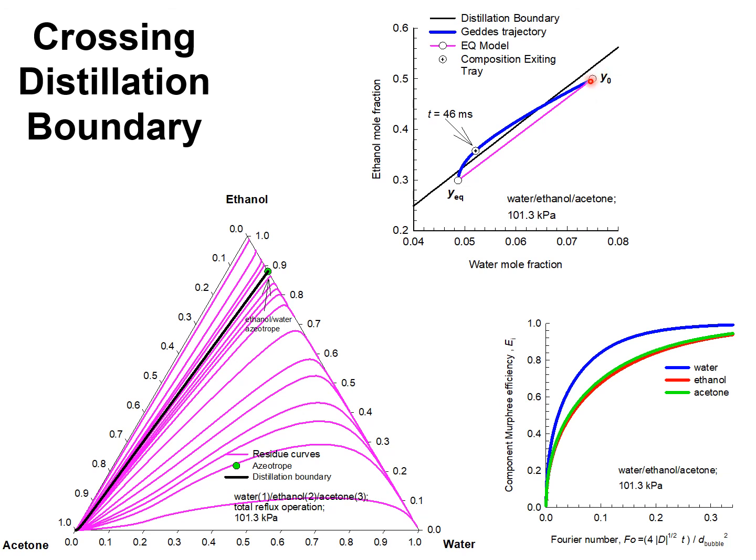However, the serpentine trajectory followed during the equilibration process stops at a time of 46 milliseconds because the froth height is not large enough for equilibration to occur. And the consequence is that the composition leaving the tray has crossed the boundary. So again, we have the same observation as in the Duncan-Toor experiments, that the serpentine equilibration trajectory is followed due to diffusional coupling effects.